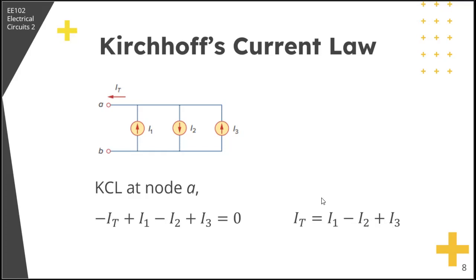So this shows that this circuit on the left can be reduced to this circuit on the right. They are equivalent, no? So based on this, we say that parallel current sources can be combined into one current source. So you just add them: if you see parallel current sources in the problems you encounter next, you can just add those current sources, taking into consideration their signs.